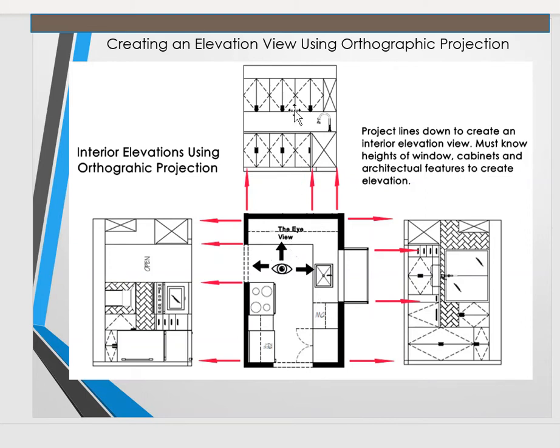As we look this way, we are looking at all cabinetries, upper cabinets and lower cabinets. And a little slice right through here. It's like a section. That X means that you sliced through the cabinetry and it's coming towards you. See how if I slice here, this cabinetry is coming towards me. It's an L shape. So it shows that it continues towards you, and it shows just the little profile of the sink. Gives you an indication that this is an L-shaped cabinet.